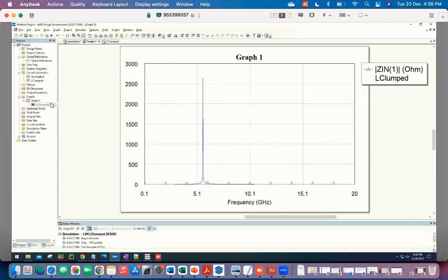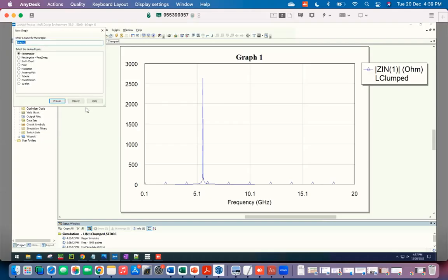But when you are looking at resonators, normally we are looking at the real part of the reflection coefficient, right? Usually in a network analyzer, that's what we measure. Of course, you can convert gamma to Z in, because that's just related by the reflection coefficient formula. Does that make sense? One can get one from the other. Even though a network analyzer doesn't measure Z in directly, it measures the reflection coefficient. But gamma is just Z minus Z naught over Z plus Z naught. Z naught is known, gamma is known, so you can compute Z. So let's look at the reflection coefficient.